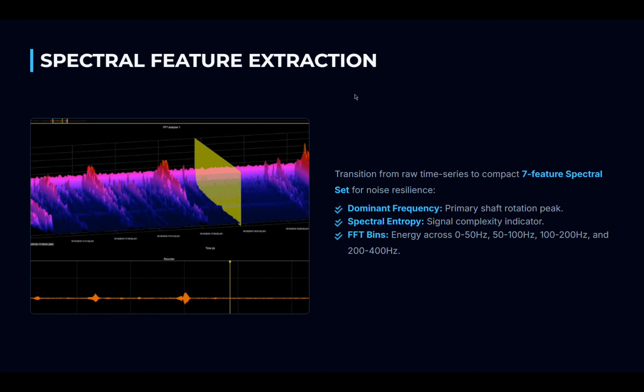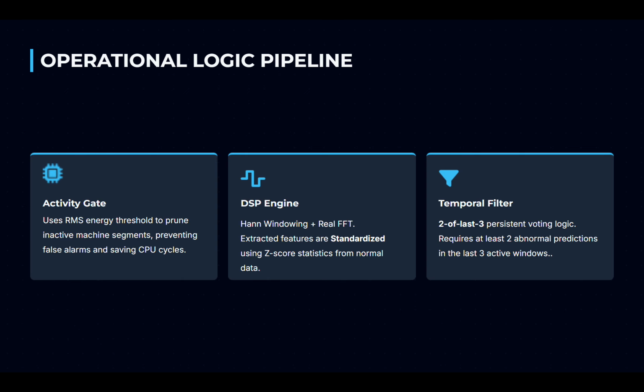So the pipeline is that once the features are extracted, they move in 3 stages. First, the system checks whether the machine is running. This saves a lot of compute because you don't want to be running analysis on something when it's off. If not, then it ignores this window. Otherwise it extracts and prepares the vibration features for the model.